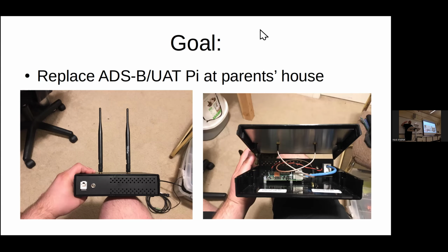And so the secondary surveillance radar will say, okay, when I pinged it, I was pointing this direction and it took this long for a reply to come back, so I know it's this far away in this direction, and there are these additional parameters. That's great for air traffic control, because now they know where stuff is. It is not useful to any other aircraft in the area, and so that is where ADS-B came in. It is Automatic Dependent Surveillance-Broadcast.